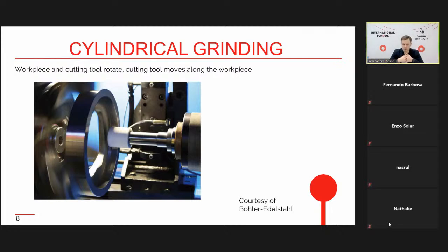Grinding processes are usually final processes. So the surface after grinding is very good. The roughness of the surface is very low, and this surface can be used for assembling different parts with each other by means of some ground surfaces after grinding.